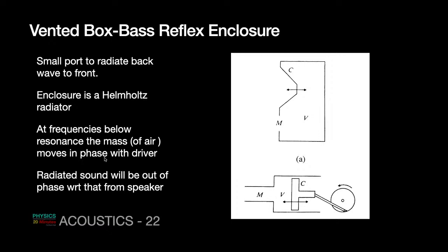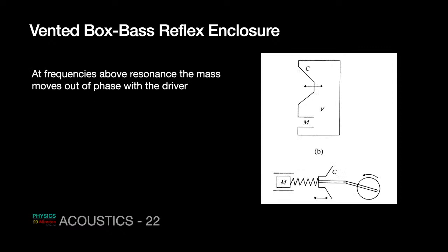So basically you have to remember the second point: the radiated sound will be out of phase with respect to the speaker. So at low frequency, the sound output will become out of phase. Like if this pushes inside, something happens here, and then a compression is created, a rarefaction is emitted, something like that. That is at a low frequency, frequency below resonance.